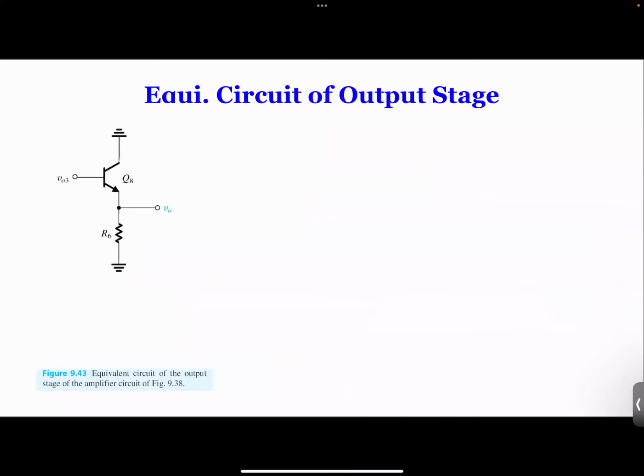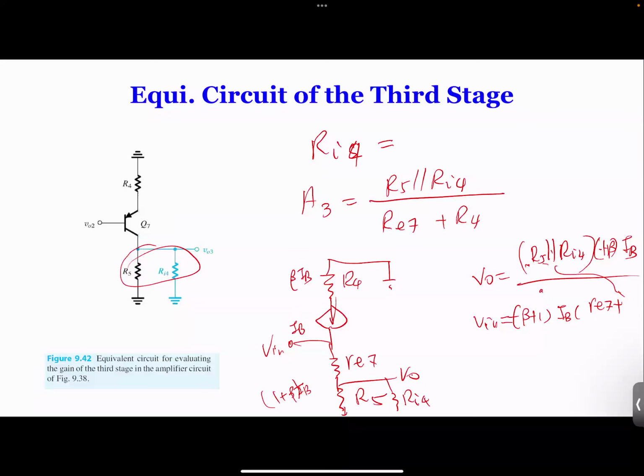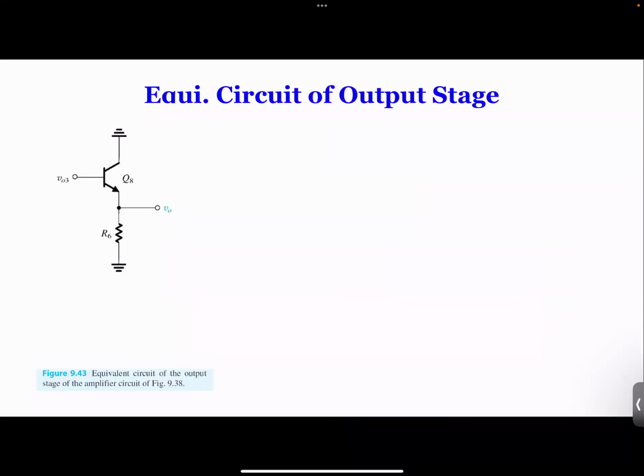So here, again, you can get the gain. Plugging this back, you get this gain, and by doing this, we find the gain is going to be minus 0.6242 volt per volt. And the last stage is an emitter follower. We already derived how to calculate the gain of an emitter follower, just at the beginning of this example, which I had as RE6.